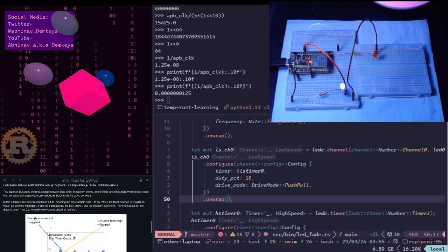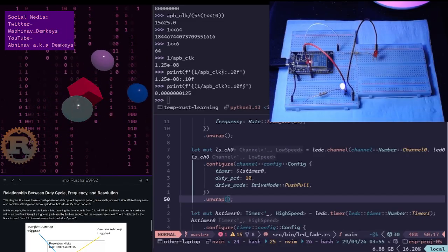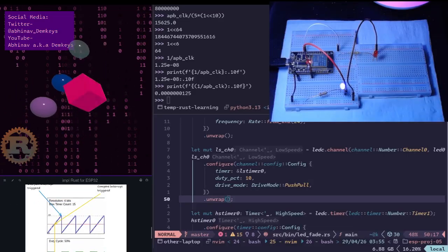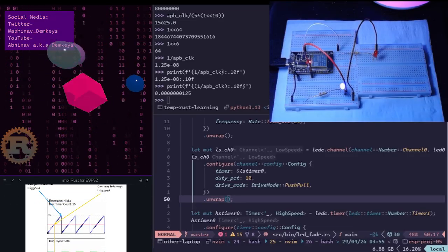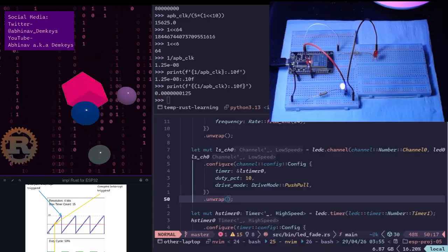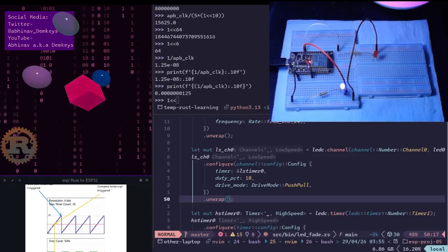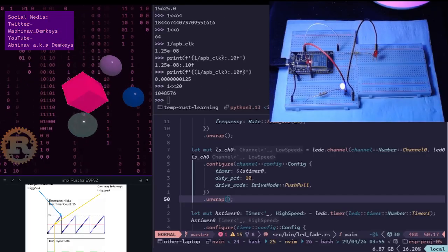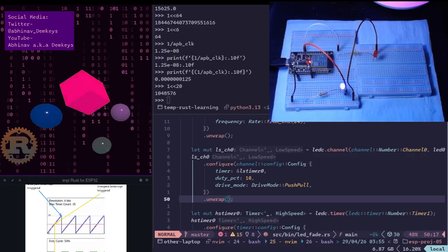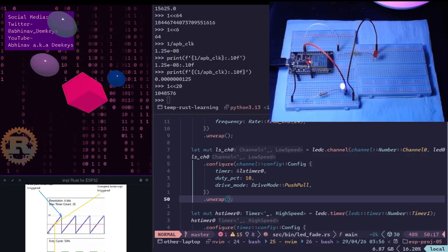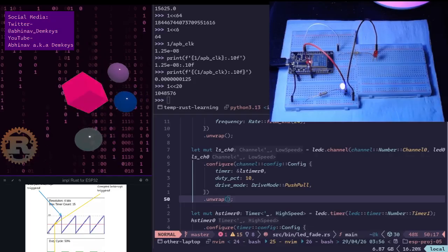I believe that's our counter. The counter register can be up to 20 bits, and 20 bits is a lot because that'll give you a lot of very discrete steps. That's 20 bits. So we would be able to divide one period into, what is that, 1,048,576 steps.